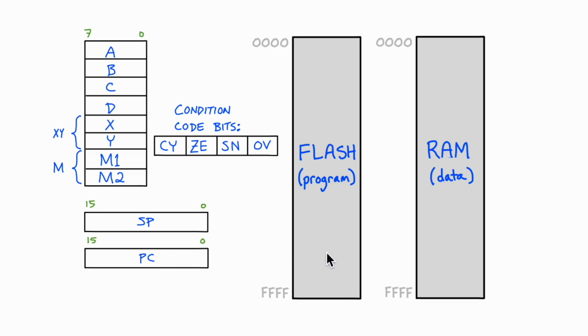The address spaces for the program and the data are uniform with no special addresses. Execution starts at location 0 in the flash memory, and in the RAM, the stack will grow downward, so presumably it will be located in high memory. Not all memory need be present.